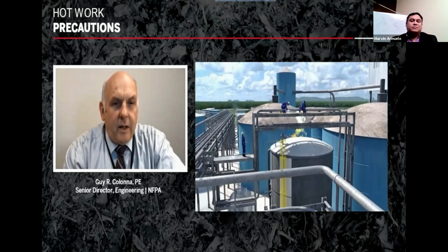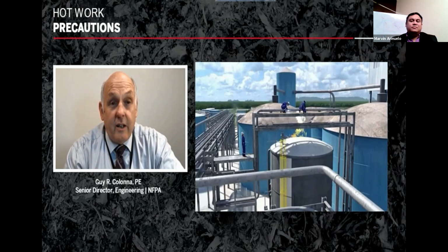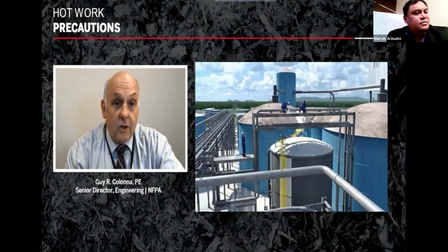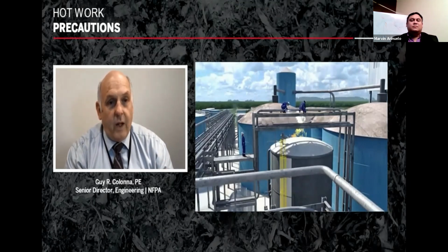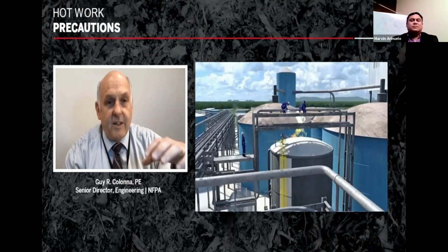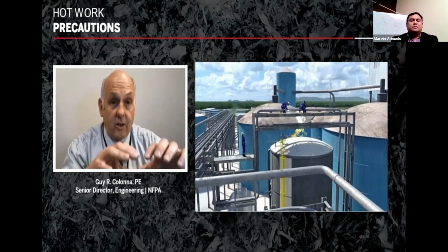So as we look further in terms of the investigation and the information that the Chemical Safety Board has illustrated through this video, one of the other aspects that is important to not lose sight of is that, as you're planning your hot work, it is important that you understand all the areas where sparks and slag can travel. So if you have high winds, they can blow greater distances horizontally. But in this instance, and any time you are doing hot work on an elevated platform, it is important to understand where the sparks and slag can be taken by gravity, because they're going to fall down.